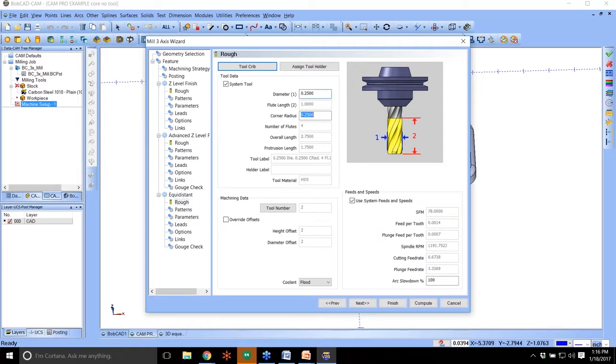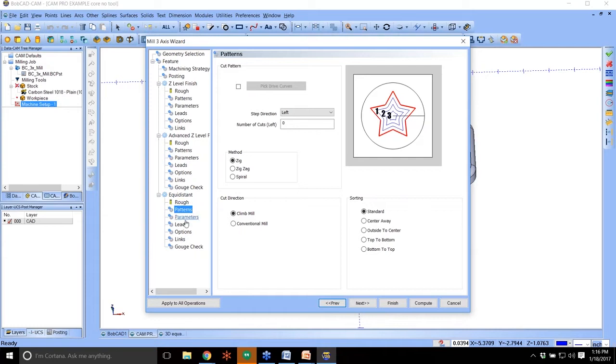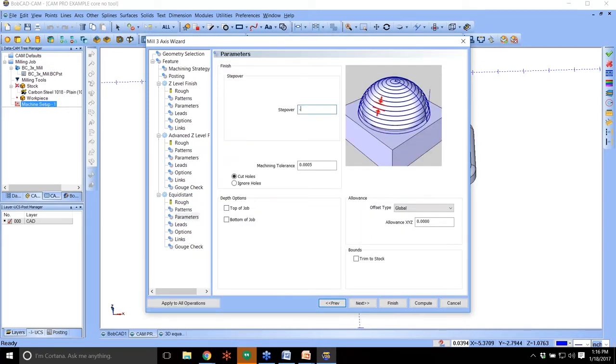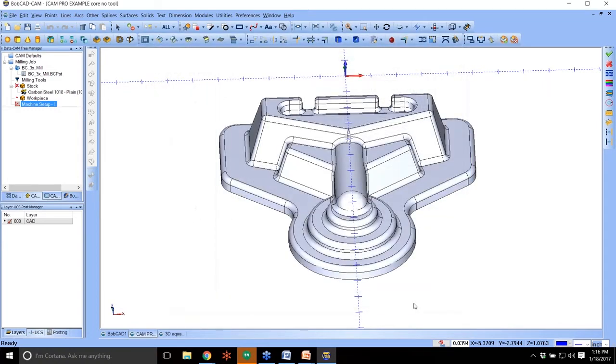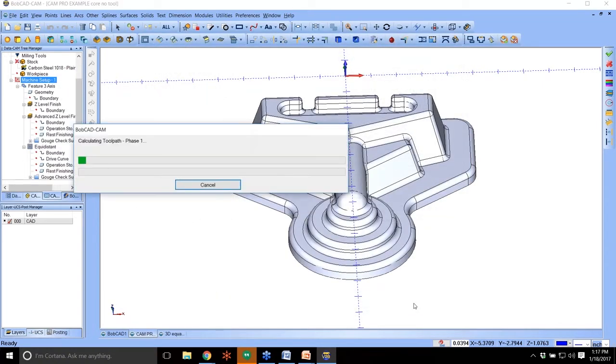And then what we're going to do is we're going to go ahead down to Equidistant now, and we're going to set this up. Now, Equidistant is designed to cut all over the model. And the reason why we're using this one for this particular setup right now is we're trying to compare 3 toolpaths to figure out what is the best and how to pick the best one for exactly what we're trying to do. So if we go ahead and we just leave it at the default and we set everything, we hit compute, we're going to calculate all 3, and then we're going to dissect it. Now, while we're waiting for that to calculate, we'll go over what we're going to cover next as well, and that way we're just kind of keeping the process going.